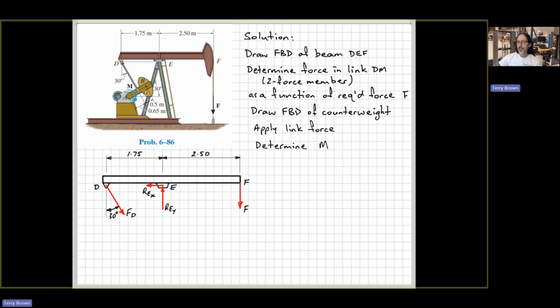And typically when we now start to make use of our free body diagram and the equations of equilibrium, we will start with a moment equation. Usually the moment equation at the pin joint, where two of our unknowns pass through, so they have no moment effect about that point. So we can find one of our unknowns straight away. I've written that here in symbolic form: sum of moments about point E, anti-clockwise positive, equals 0.